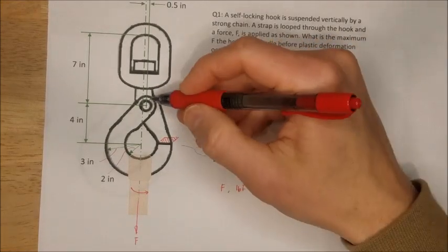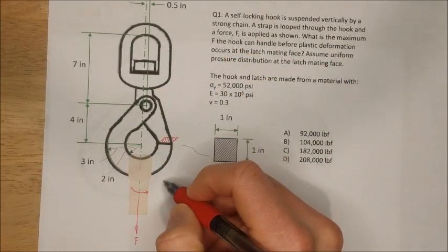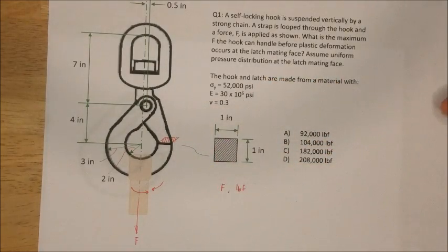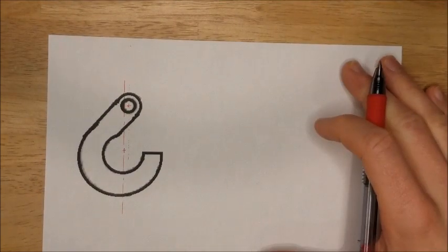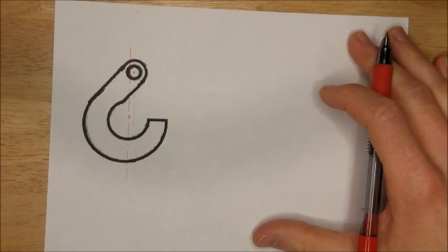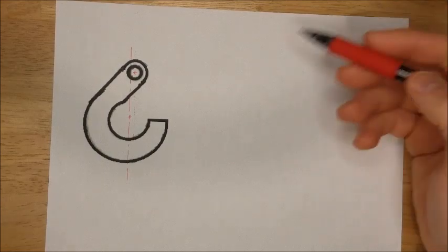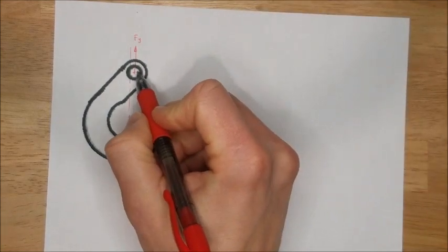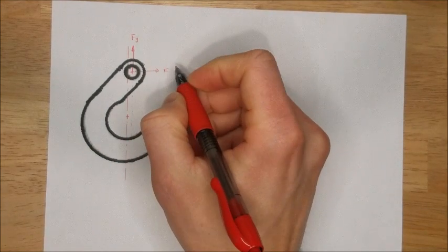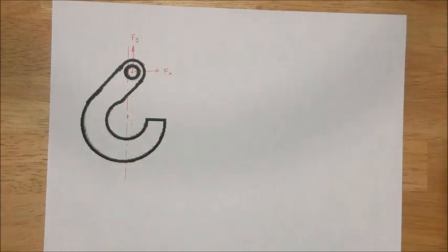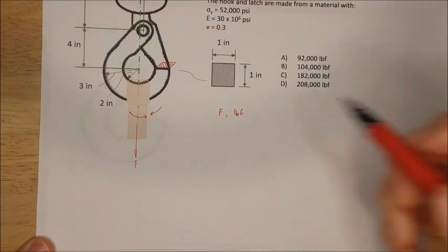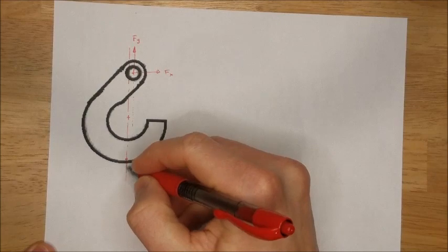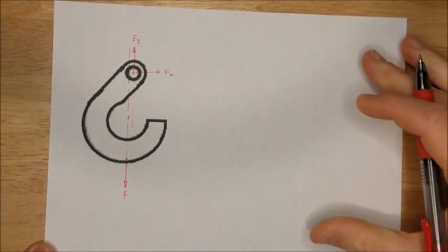So there's a force coming from the latch or applied from the latch that's forcing the F back to the center line. That's why this is self-locking. So I've selected the hook here to draw my free body diagram with. And we're going to just start simple. We know how to do pin reactions, so we've got a force in the Y direction, and we've got a force in the X direction. Now, I'm going to make an assumption here, and take this strap, and I'm going to apply this force straight down. As long as it's in the center line, I don't think we have any troubles.